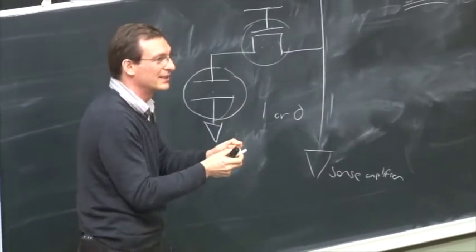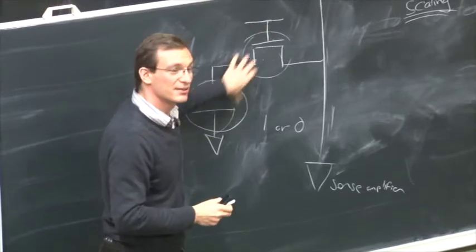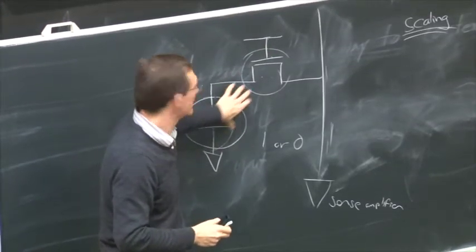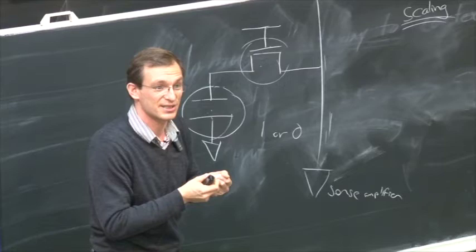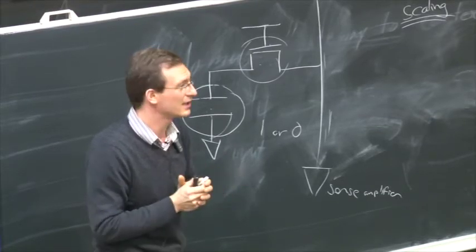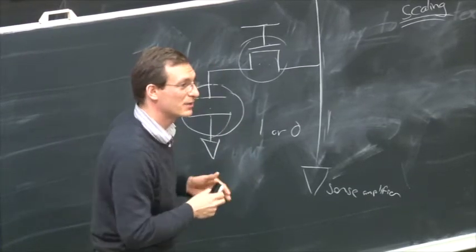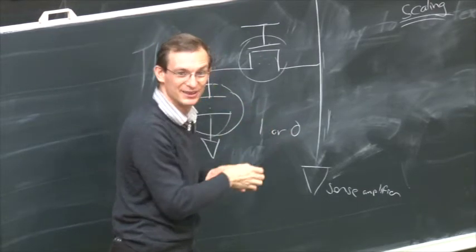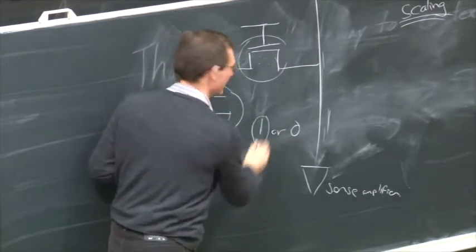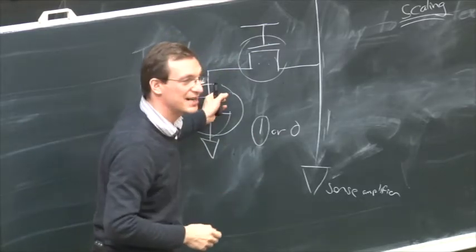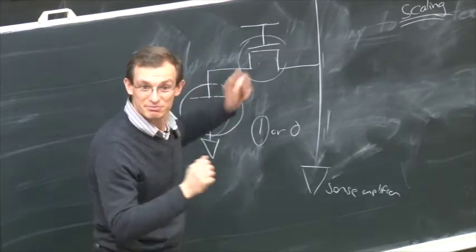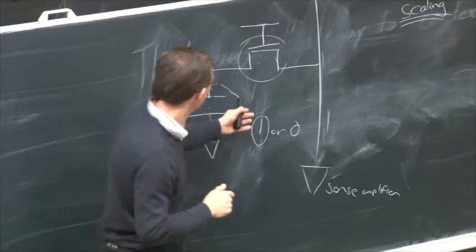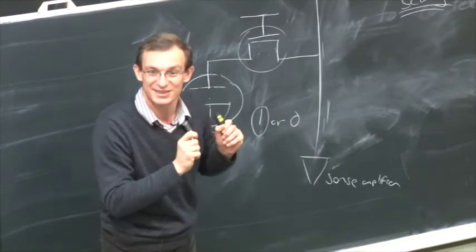And this also becomes unreliable. Once you make it smaller, the noise margins reduce, which means that this becomes more prone to errors. It becomes easier to flip the charge in one way or the other. So you may actually store a 1, but maybe a particle strikes and it turns to 0, right?